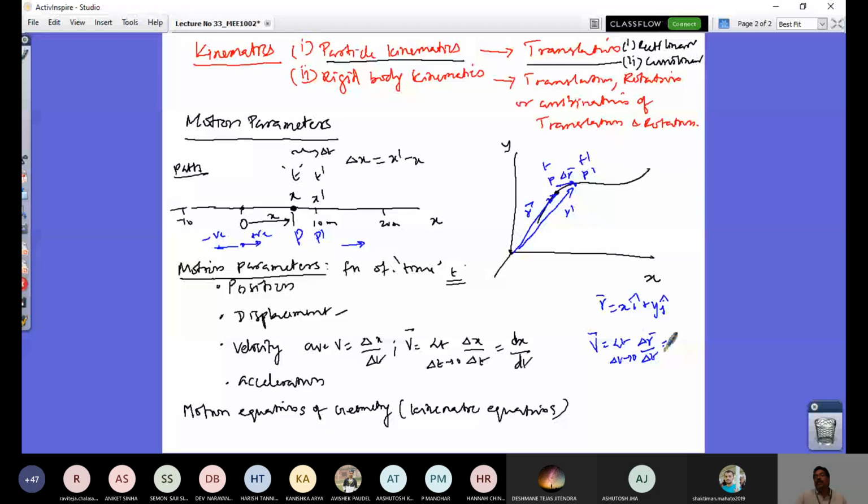This is in 2D motion, or it is called curvilinear motion. So one is rectilinear motion, another is curvilinear motion. Here, to define your position, only one coordinate, position x, you are using. Whereas here you require the x as well as the y coordinate, and that is the position vector. So the change in position vector over the time difference, the ratio, is the average velocity, and when the time difference approaches 0, I look at an instant, and the derivative of the position vector gives you